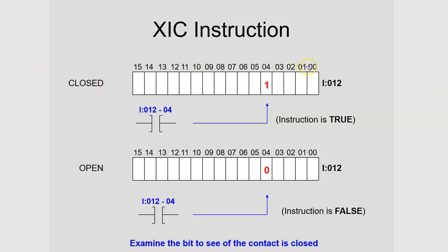And this 0 to 15 is 2 bytes, or we said for us a word is going to be 16 bits. So the reason is, again, our PLC has 16 screw terminals on the input module, and those screw terminals are mapped directly to these bit positions in the input image table. And so here's how this works.